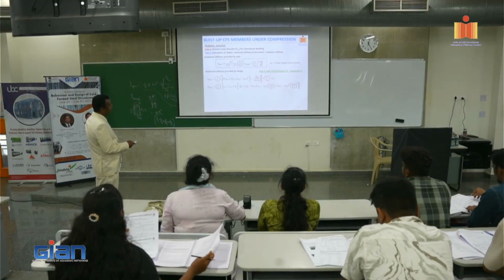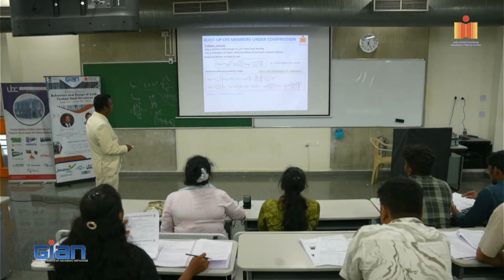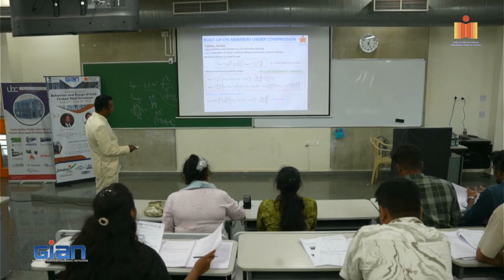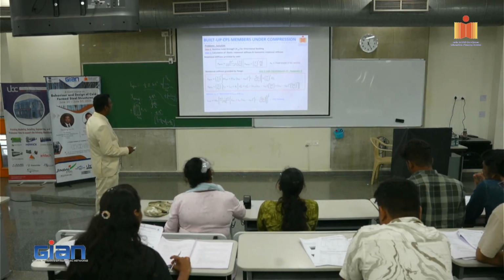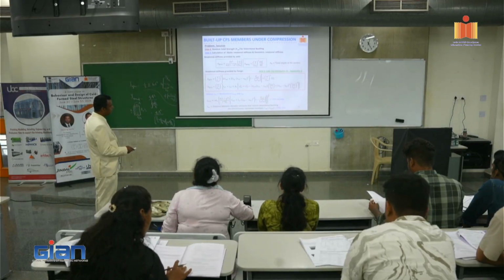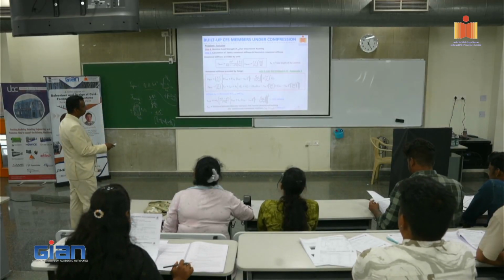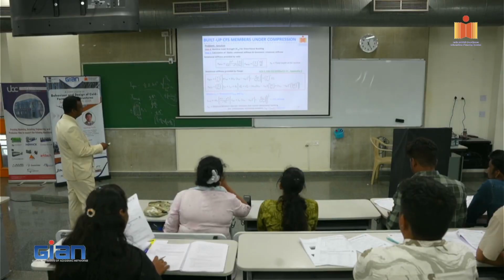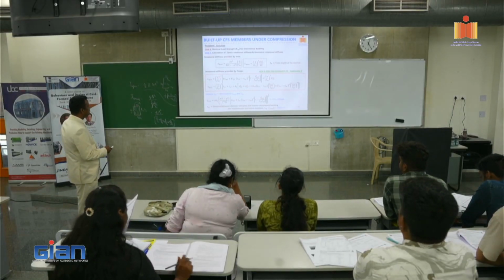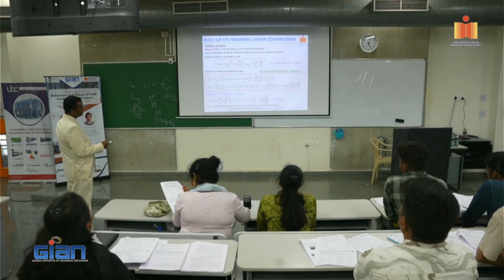Here you have another value, LD. LD is given as the minimum of LCRD and LM. So you have to calculate LCRD. There is an equation for this, which gives 502.44, and LM is the distance between discrete restraints, which is 1800. The minimum of the two is 502.45. So that is the value you have to use here, right? Here and here and here, in order to calculate KFE, FE and KFE, FG, right? For KFE, WU, you don't have to worry about it. It is very simple. You can just use this.